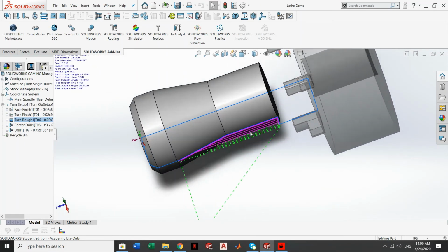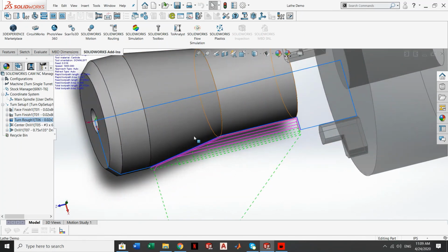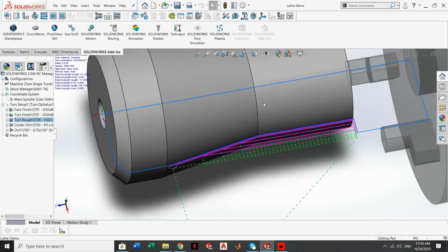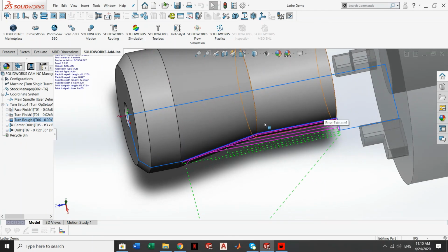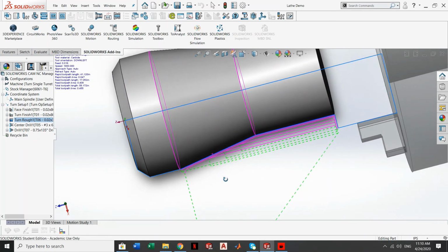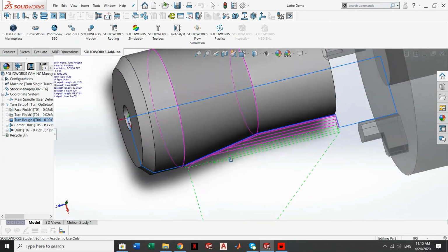Next we selected both these two faces because this procedure will be conducted all at once, and using a larger tool, the 80-degree carbide end bit, the tool was not able to actually reach the entire geometry, and therefore this pink line appeared further out and would not cut all the way in. In order to mediate this, we chose a 35-degree carbide end bit, which allows for more close cuts and finer geometries to be cut into this part. As you can see, this will occur in multiple passes as it's working the stock down to its final shape.